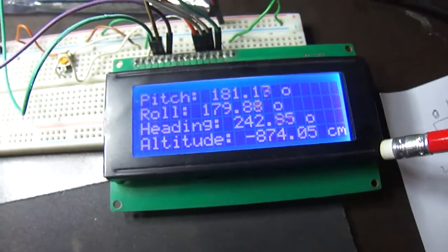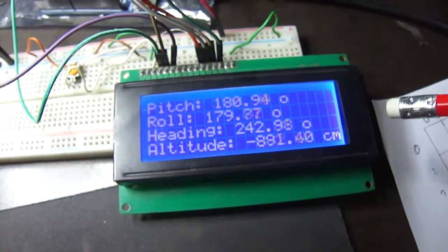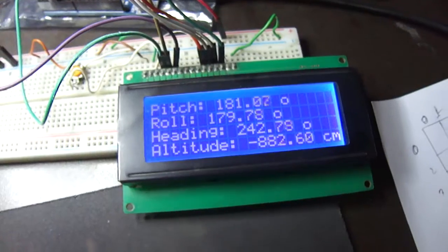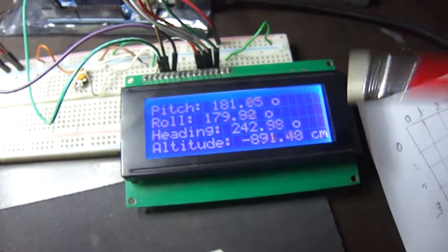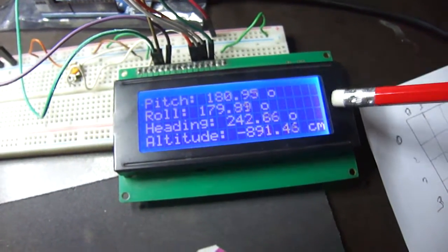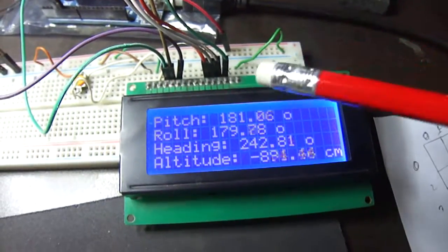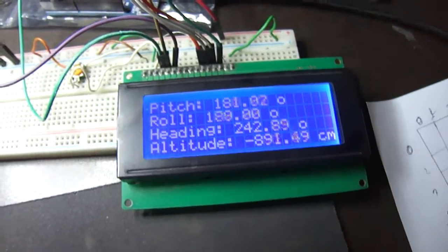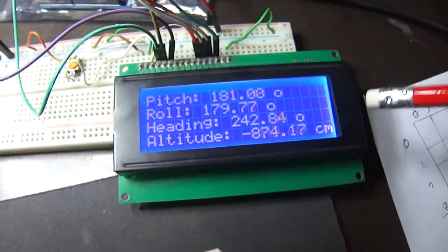If you need to display it, I suggest going with an SPI or I2C LCD screen, which will greatly enhance performance, in the sense that the microcontroller will need to do less work and can communicate much faster, against this one, which uses only 4 bits in the LCD library that I have used, which was provided by Arduino.